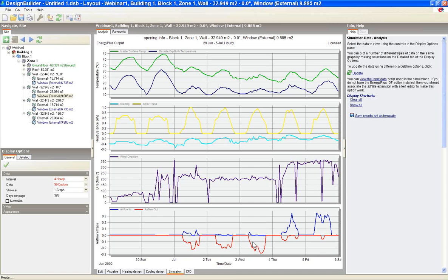And I think it's quite important to pick those sorts of details out. So we can actually show that even within EnergyPlus. We can look at the bulk airflow and look at what is predominantly happening. So even this information could be relayed to show what the typical situation is, over a week or over some typical days. And in the UK, where that might be the predominant wind direction, that would be quite an important thing to highlight to people. But you can see that we've got this information in the model now.